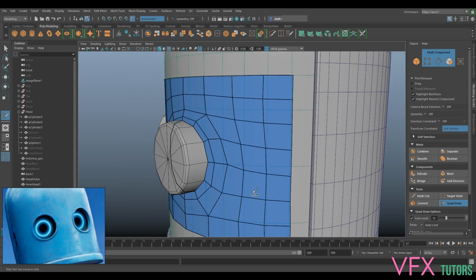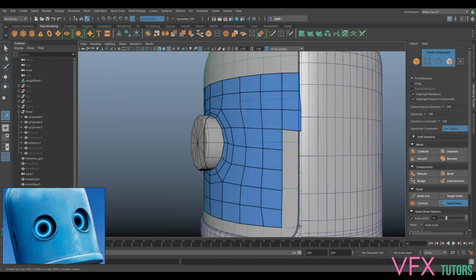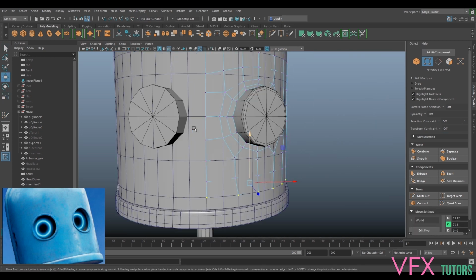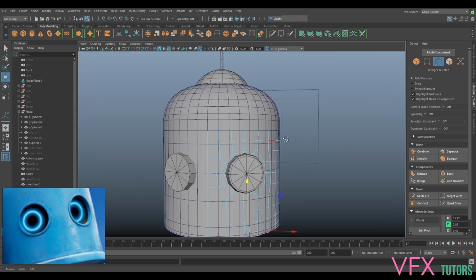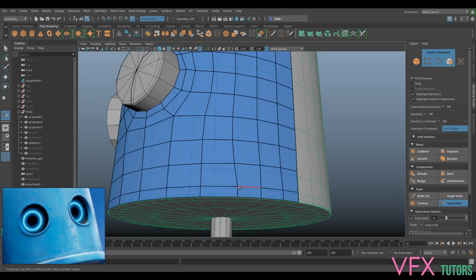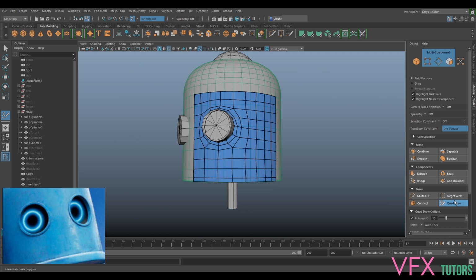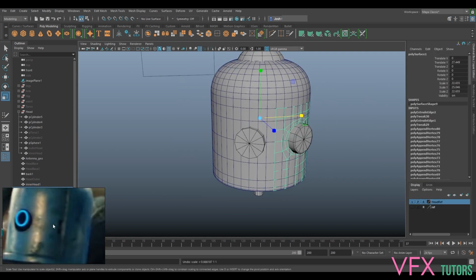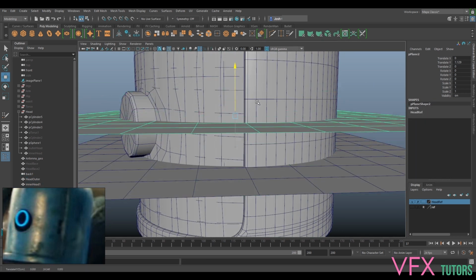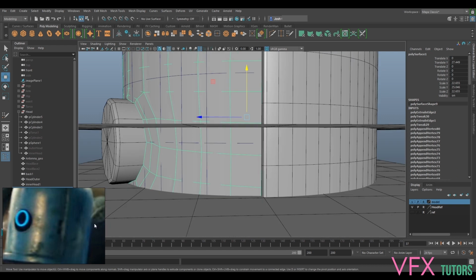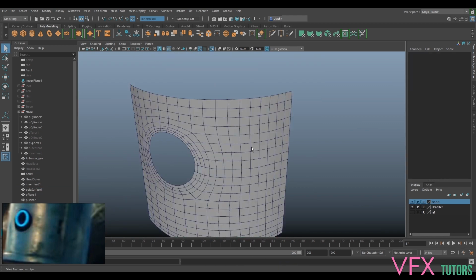We probably could have done this quicker with a bend modifier, making it whole. But the thing is, with the bend modifier, you have to have an equal amount of edges for it to bend without kinks. Whereas this way, it'll always relax. It takes a little bit longer, but it almost guarantees you a much cleaner mesh. And you'll notice that I use these planes as placeholders to build extra geometry around, because it's just easier to snap to geometry sometimes.